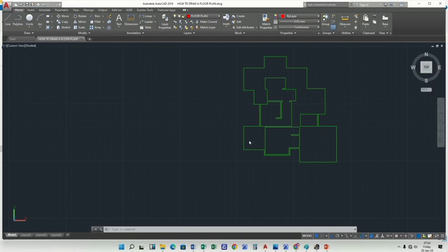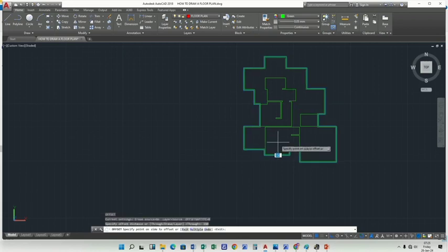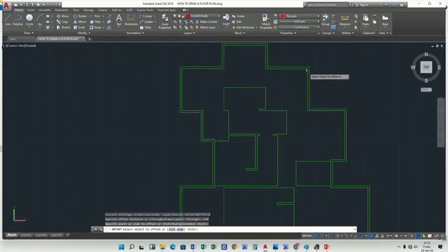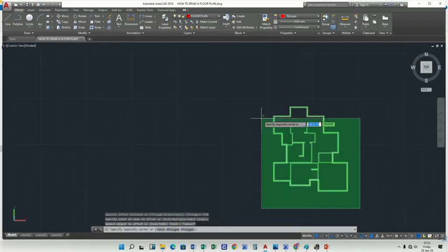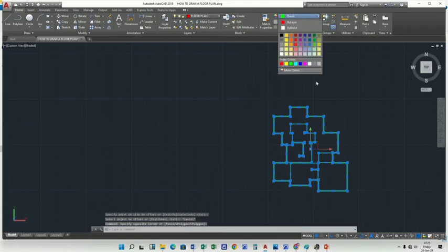And with some walls. So after here, I'm going to offset the walls. I'll offset the walls by selecting and highlighting everything, and then clicking offset distance 150. I've offset everything just like that. You've seen the walls are double now, meaning the thickness of the walls is 150 millimeters, which is 15 centimeters.